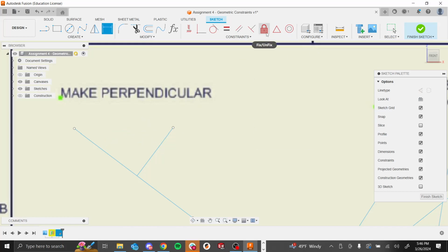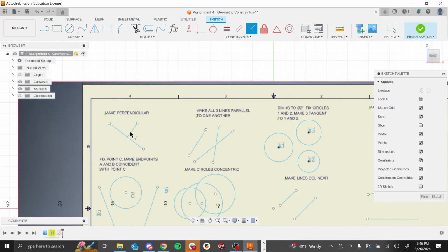So yeah, these geometric constraints are really useful. When I first started CADing, I didn't know about them, and I just used sketch dimension for everything, even for things that were coincident. So I'd set distances to 0, and then it would freak out and break the CAD. So please don't do that and use coincident or all these geometric constraints.